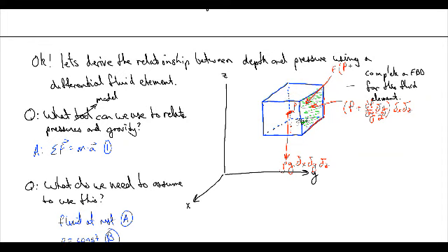Now we've got to add a change because we're on one side of it. And unfortunately, we're in the negative direction now. We're on the back side of this cube, right? We're going from here to the back. So we're going to have a minus dP/dx times delta x over 2, right? Because if the pressure is rising in the x direction, on this side, acting in this direction, we would be adding that change, and on the back side, we have to subtract half that change. So we have a dP/dx, which is the change.